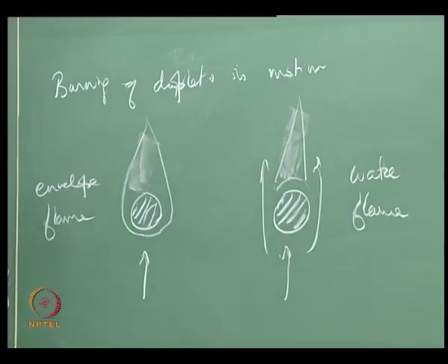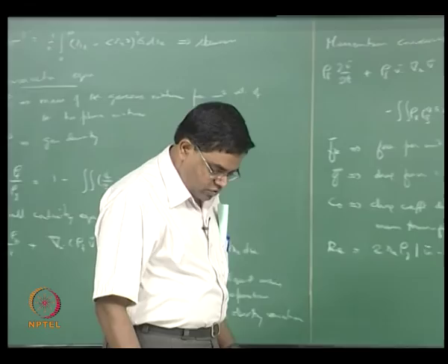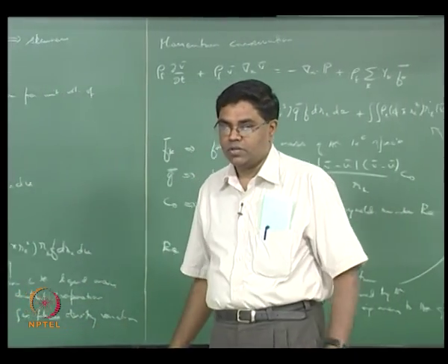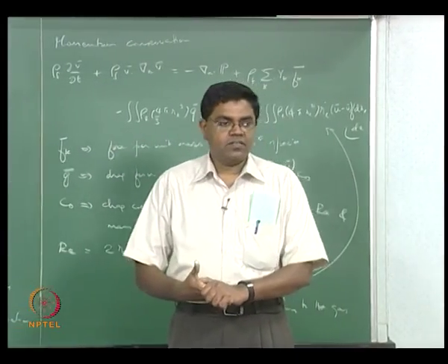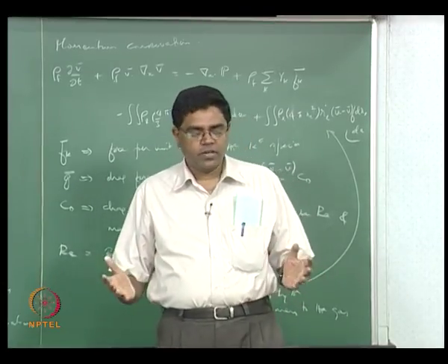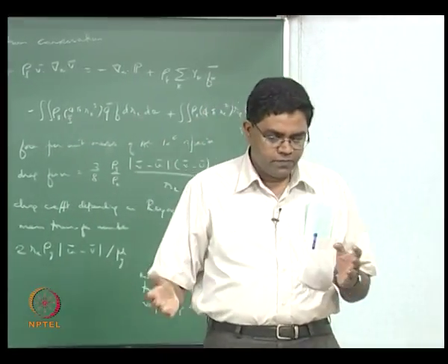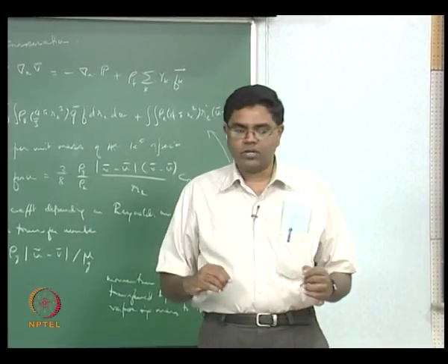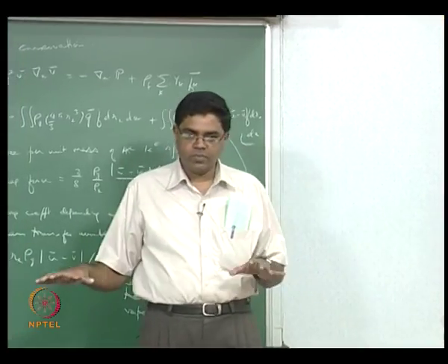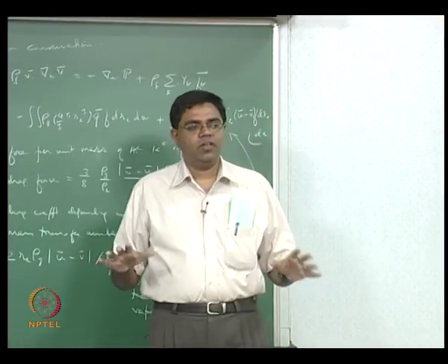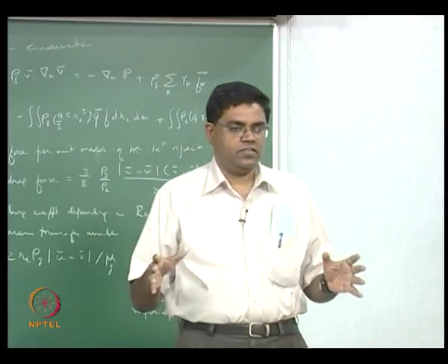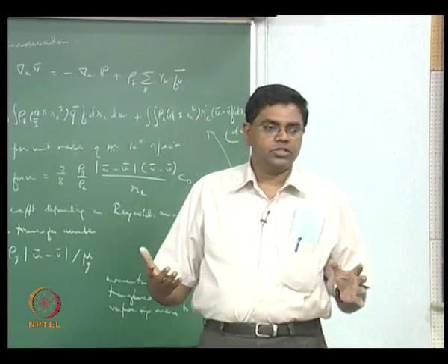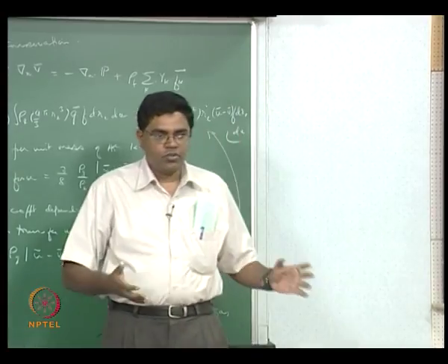Okay. I want to stop talking about droplet combustion, but we are still in the subject of what's called heterogeneous combustion. That means we are talking about some of the reactants, or some of the chemical species in general, being in a different phase compared to the others, right. So far, while we were talking about droplet combustion, it was all homogeneous combustion. That means we were typically talking about all the species being of the same phase, and that's the gaseous phase. But the moment you start talking about droplet combustion, we are beginning to step into heterogeneous combustion.